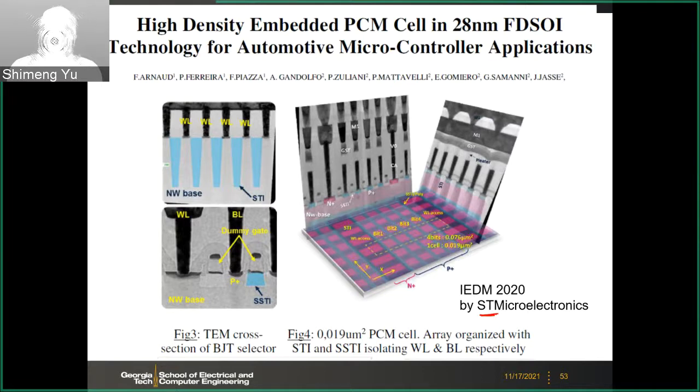For the automotive MCU, when you use that under the hood, above your engine of your car, the non-volatile memory has to sustain very high temperature. It needs to be much more reliable than your commercial grade product. You need to reach even up to 150 C in automotive electronics.